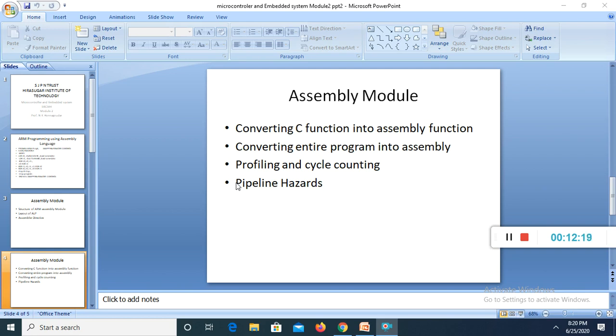After optimization, we can measure the performance improvement by using a cycle counter to benchmark a given subroutine before and after an optimization. The ARM profiler works by sampling the program counter, PC, at regular intervals. The profiler identifies the function the PC points to and updates a hit counter for each function it encounters.